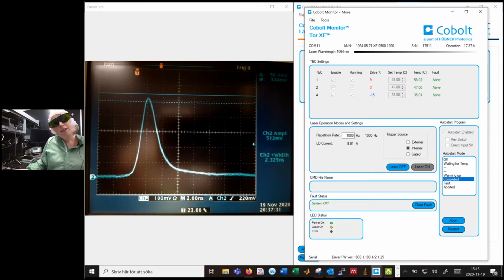Looking at the pulse we have coming from the laser now, as you see here on my oscilloscope, the pulse is about 2.2 nanoseconds long, and it is measured so that we're sampling over some hundreds of pulses overlapping, so that we can see also how the stability of the pulse looks. I have put some cursors here to illustrate what would be a peak to peak of roughly 10% variation, and as you can see, we're well below that. So this laser runs very smoothly in this way.